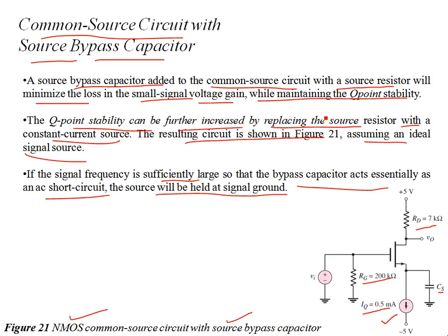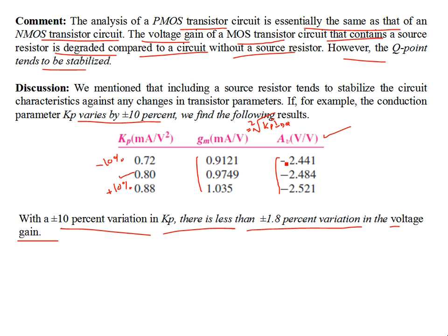So now you see, if you compare this 9.9 with the voltage gain that we had without the bypass capacitor, it is large. Okay, so it's important to include the bypass capacitor to have the full swing of the output voltage that we require, and of course stability in the transconductance gain and the voltage gain.